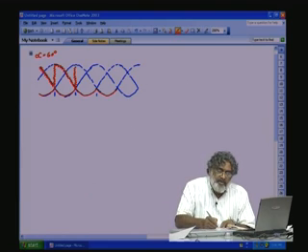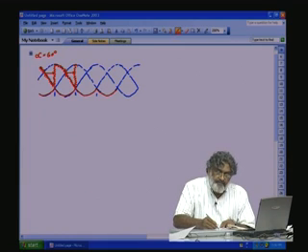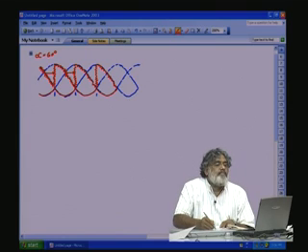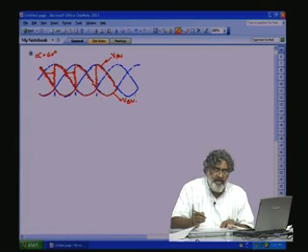So every 60 degree it starts from here. Similarly, this is 60 degree. It will come here. So this is the ripple. This is the VAN ripple and this is the diode, that is the VBN ripple. So VAN minus VBN, if you plot the instantaneous value, it will be like this.